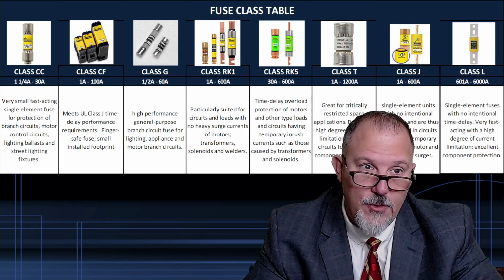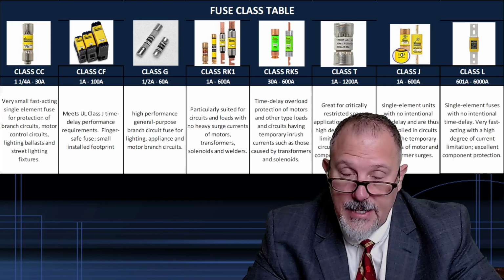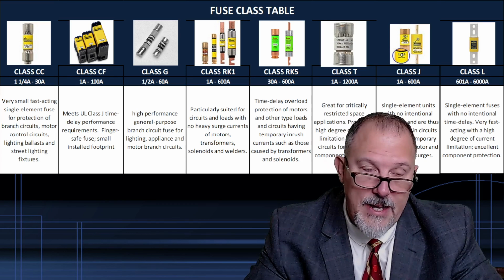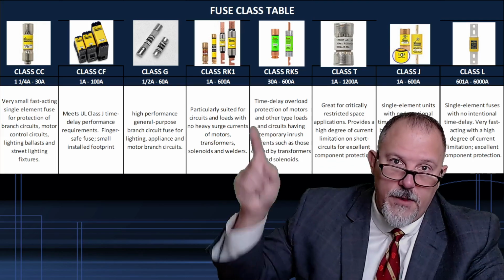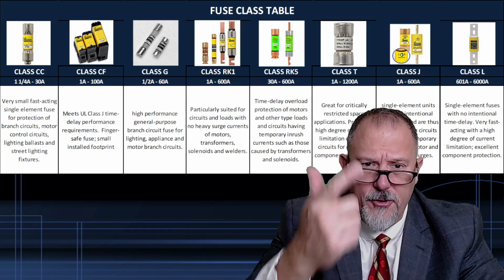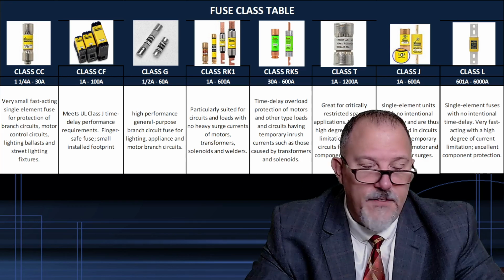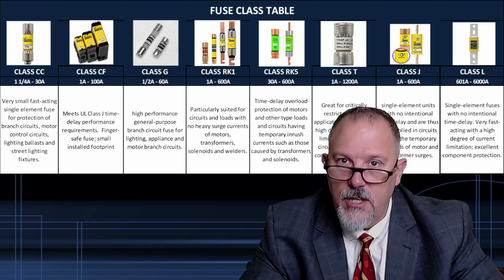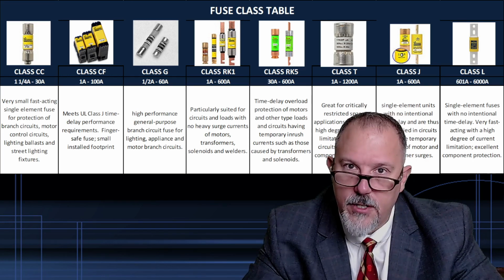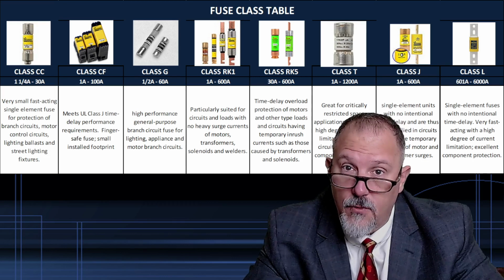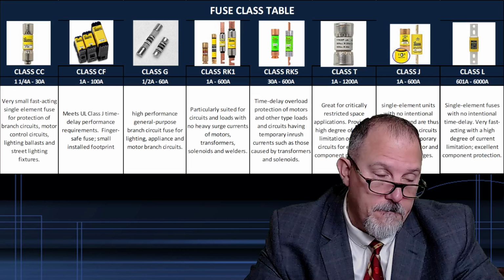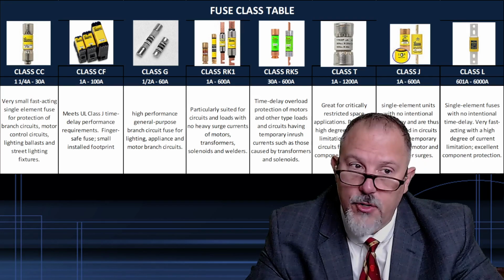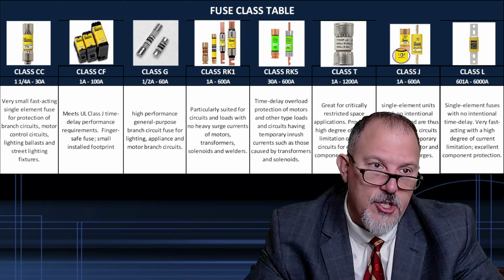So when you hear a Class CC, I nicknamed that Charlie Chaplin because of the little dimple at the top. That's way over there on the right, or on your left. It's the CC fuse. You'll see those on control power circuits, in control transformers and things of that nature. Little PTs, control power transformers. You might see them in street lighting fixtures.